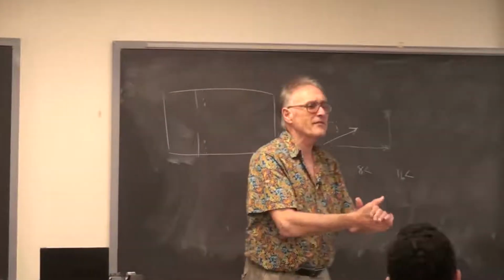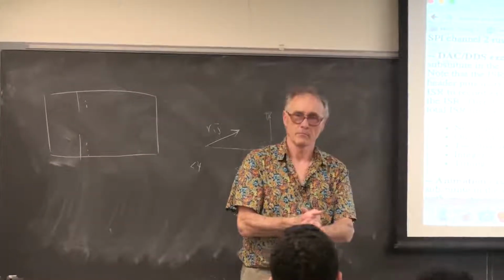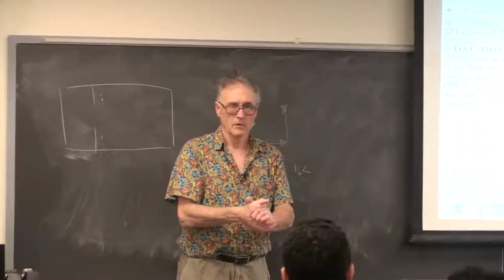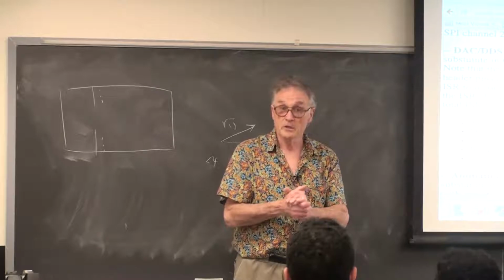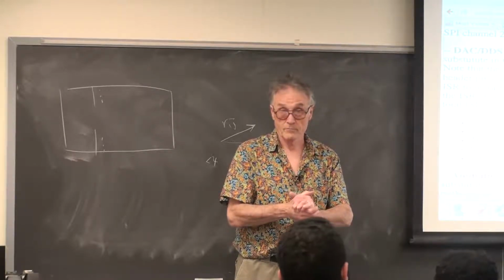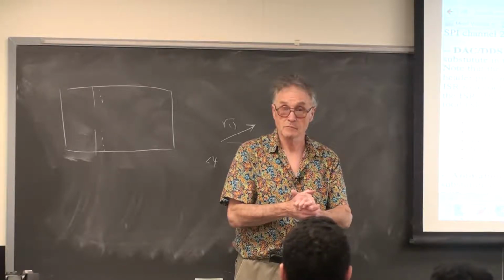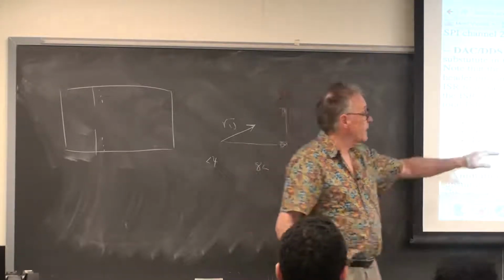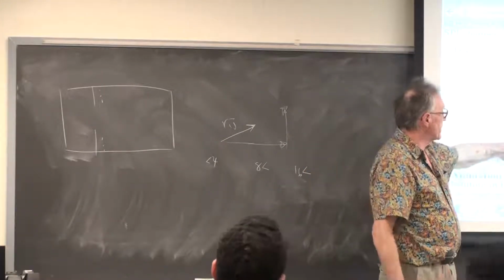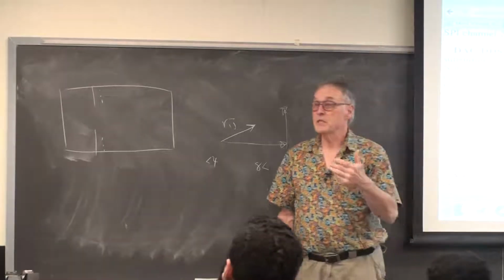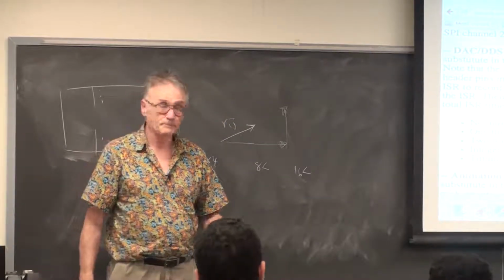It has to save the registers that the floating point unit uses. Okay, but you said it was in or out. Right. It has to save them going in. It has to restore them going out. So it's symmetric. Okay, so I still don't really see how going in would take more time based on the operation inside the ISR. Because the reason it takes longer depending on the operation inside the ISR is that the floating multiply takes more registers to actually do the multiply, and the compiler notices that.